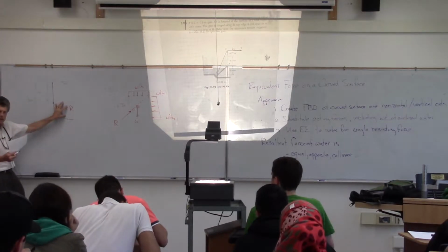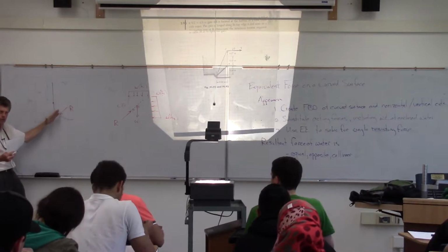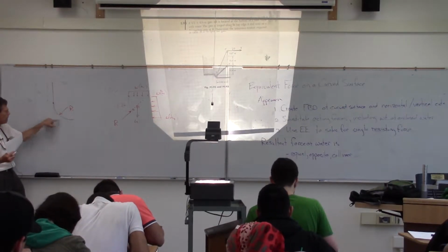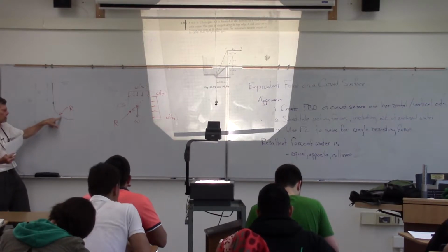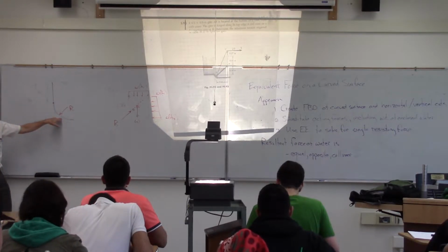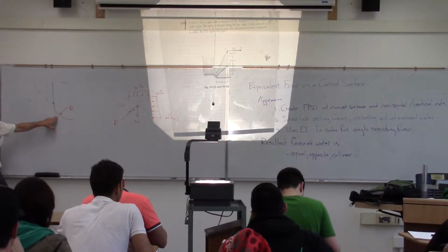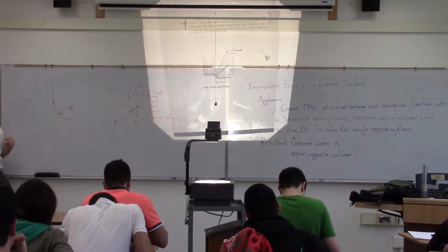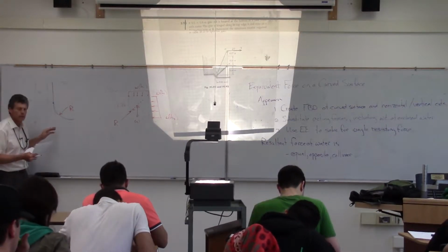What I'm saying there is, if we think of it as a two-force system, the water is presenting a force in the equal, opposite, and collinear direction on the gate. So this is the force we want to use in solving it, although even if you use this one, you just switch signs. It's going to be the same direction and magnitude, just the sign is different. But this is the one acting on the gate, and then we do our moment calculations, and we'll see that when we go through this example problem.